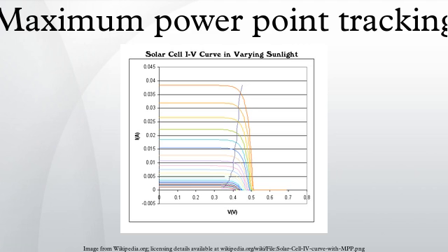Perturb and observe. In this method the controller adjusts the voltage by a small amount from the array and measures power. If the power increases, further adjustments in that direction are tried until power no longer increases. This is called the perturb and observe method and is most common, although this method can result in oscillations of power output. It is referred to as a hill climbing method, because it depends on the rise of the curve of power against voltage below the maximum power point, and the fall above that point.